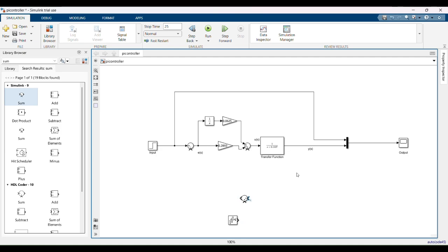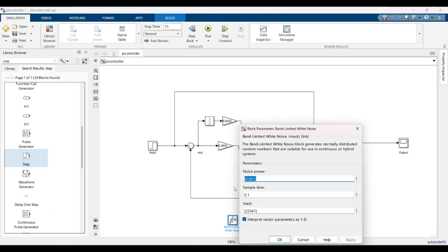So this connects to this. And this connects to this. And this is going to go in here. And what else? Let's move this here. I'm going to add another summing point, CTRL-R, rotate, put it here. I think it was 0.001.